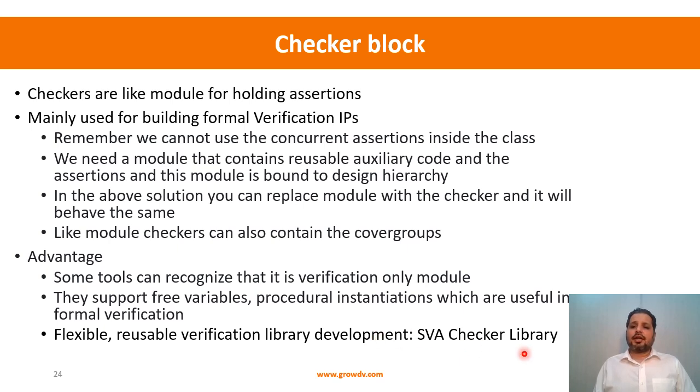A bunch of reusable properties and sequences have been put in this SVA checker library. Whether you use it or not, you can have a look at it to understand the different ways the sequence operators and property operators get used, so that when you create your own assertions, you can benefit from that. You can look it up on the web. So that's the checker block. If you build formal verification IPs, you can look deeper into this construct.